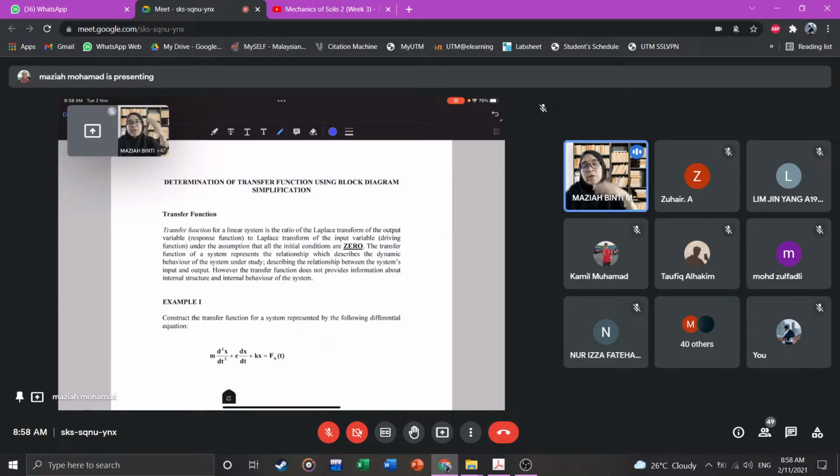First step, of course, Laplace transform. You convert your final transfer function into Laplace form, and then you solve for the parameters using the partial fraction method, and then you will inverse back the Laplace transform into the ODE again. So the final equation in ODE form is actually the time response and also the transfer function for the system.